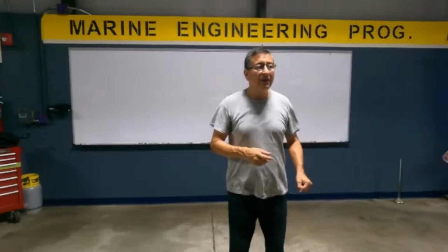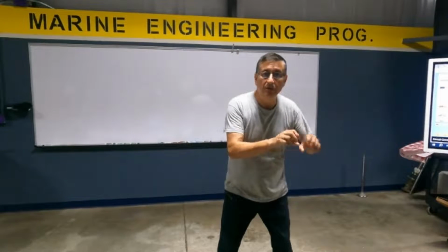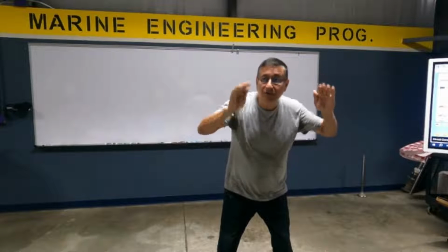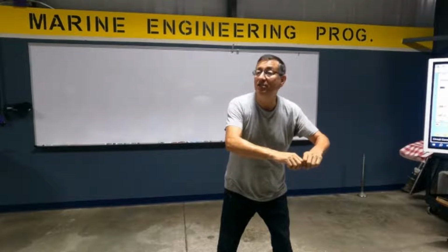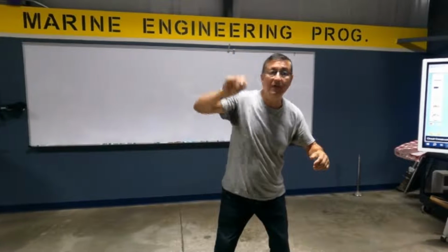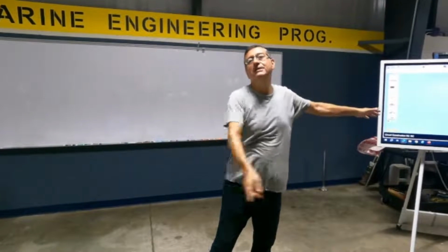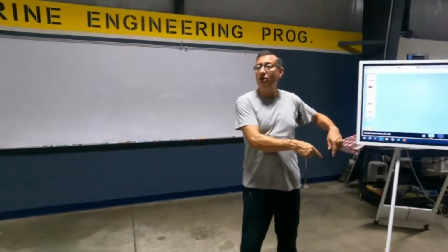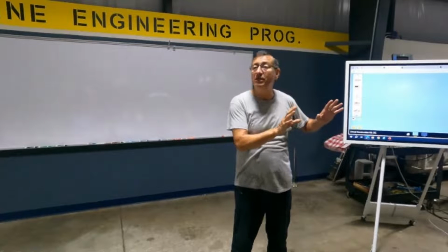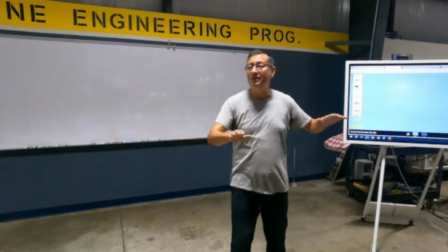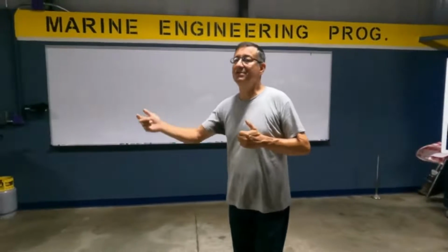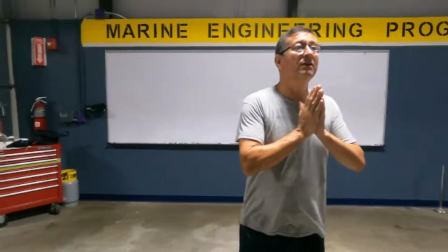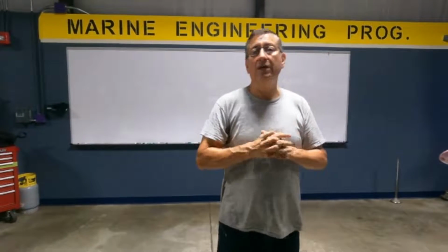What happens if the second sensor, oil pressure, sends low pressure in the oil? Immediately the sensor opens, activates the computer, and turns off the engine, because it's in series. This is a good advantage. If the temperature sensor, number 3, senses problems with the temperature, it kills the engine. This is the advantage when you connect in series in circuits where you need this protection. This is a good idea.